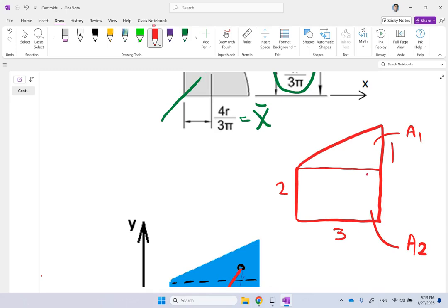So if I say, where is the centroid on this shape, what would you do? This is what you can do even visually without even physically calculating it through that formula. You say the centroid of the rectangle is right here. The centroid of the triangle is there. Okay? As I said, you connect these two with a line. Now, where along this line it is going to fall, it is related to their areas.